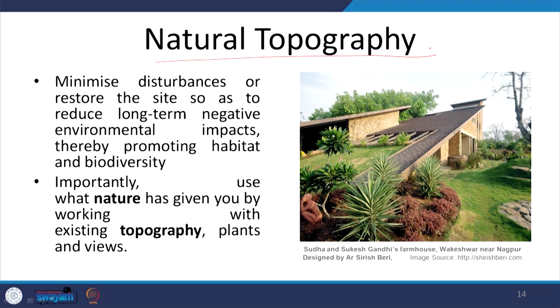Earlier, all the low lying areas in the cities were actually used as surface aquifers, water bodies. That is why we see in the majority of villages, even today, that the ponds are actually the low lying areas. So, naturally all the water is going to go and get retained there. With the help of a small bund or a small boundary around the pond or the low lying area, it will be able to hold all the water which will come running to it.